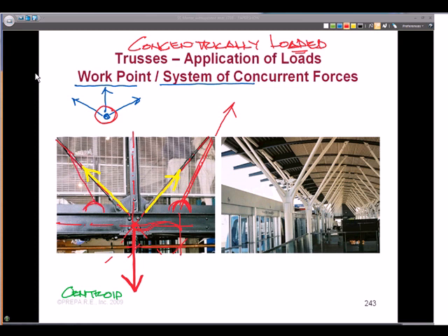Okay, we wanted these braces to be spread out, and that's what gave us the yielding mechanism. Typically, you want concentrically loaded systems, but in terms of a seismic system, an eccentrically braced frame is a good system to dissipate energy through bending. So that's where our conversations are a little bit different with these.